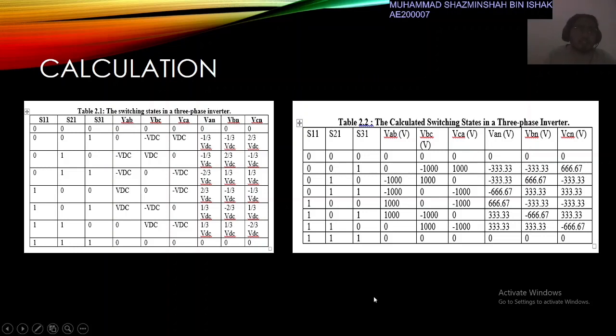The inverter has 8 switch states given in the first table, as explained earlier, in order that the circuit satisfies the KVL and the KCL. Both switches in the same leg cannot be turned on at the same time as it would short the input voltage, violating the KVL. Thus, the two switches in the same leg are complementary.